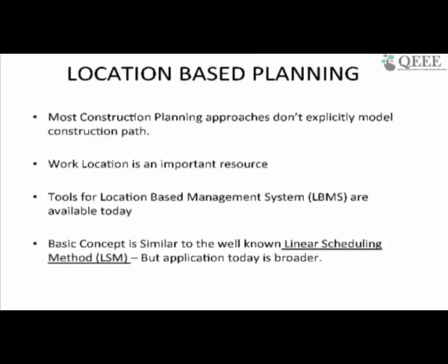Kind of ironically, it used to be popular in the earlier years. It lost popularity with CPM coming in. Basically, the key word here is location: work location is also a resource. None of the CPM techniques which we use can use the location. Space as a resource is not modeled. In LBMS, space is also modeled as a resource.